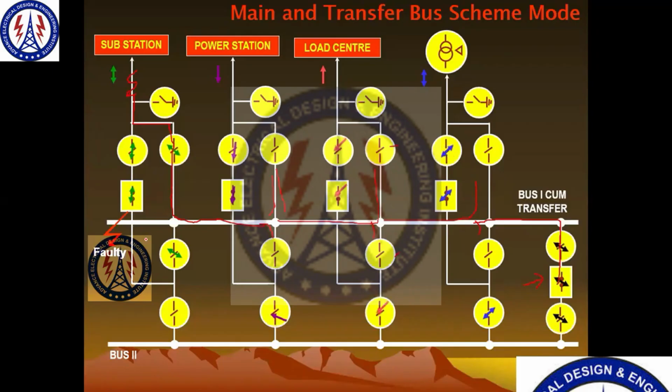So you need to check how the fault current is flowing, and where and where it is connected, basically from the healthy condition. So healthy, unhealthy: the healthy part will be isolated wherever the unhealthy part is. But sir, Pavan sir, in this case, if this coupler circuit breaker fails to open or clear the fault, then all the other stations where the power is coming from will be feeding the fault continuously, right? And there won't be any other option to isolate the faulty part.